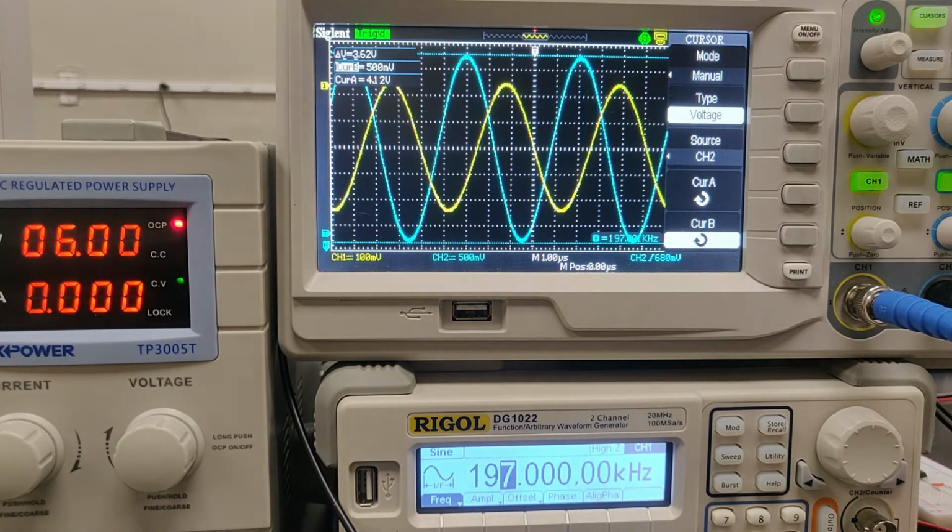In this next part, if you look at part 8, we are asked to, given that we know what this equation is, find a new resistor such that our gain is around 30. So previously, when we just did this, our gain was around 10. And we're going to be substituting the 10,000 ohm resistor for a 27,000 ohm resistor. So maybe this is also pointing you in the right direction. I think the lab manual suggests that we can use the potentiometer, but I'm just going to grab a resistor that's close to the value that I want.